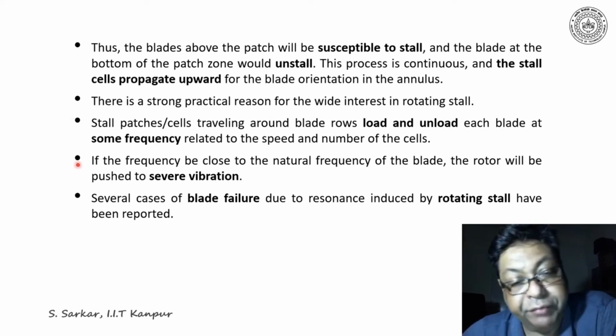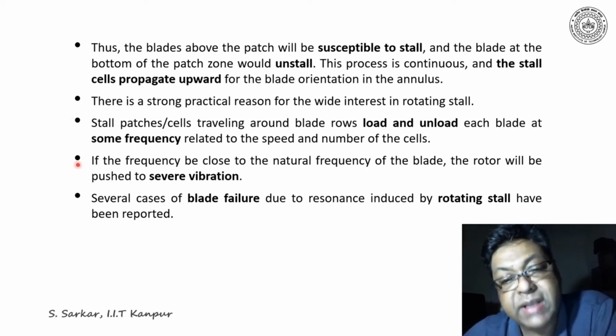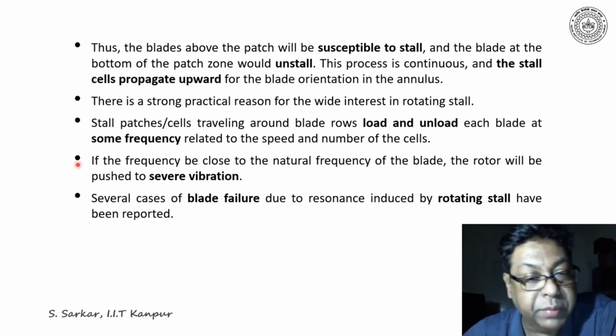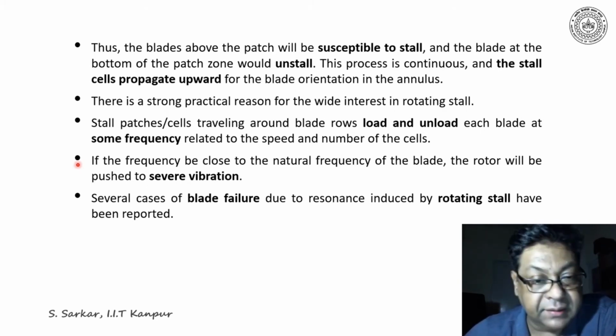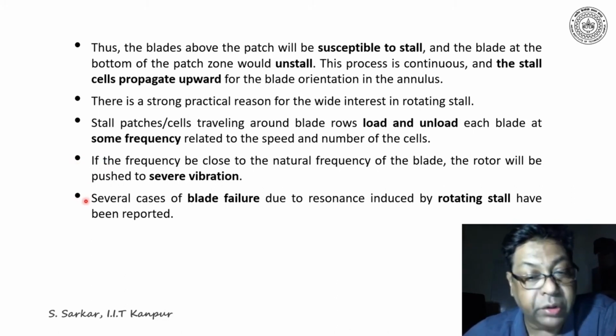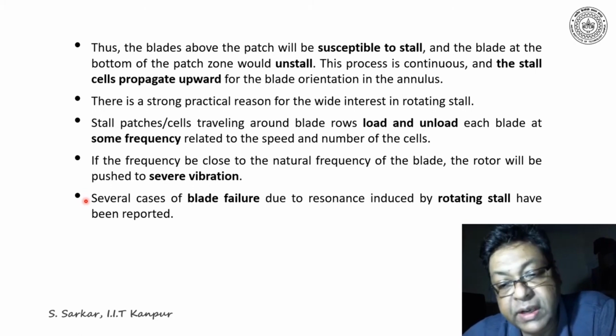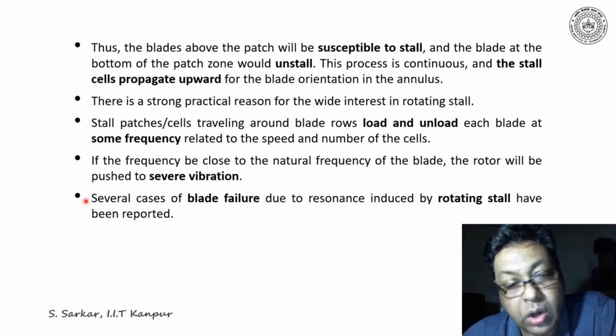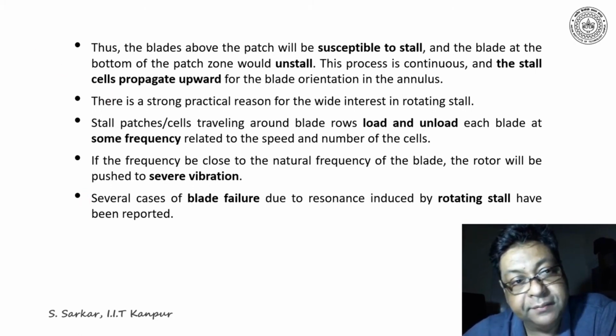If the frequency is close to the natural frequency of the blade, then the rotor will be pushed to severe vibration. Several cases of blade failure due to resonance induced by rotating stall have been reported.